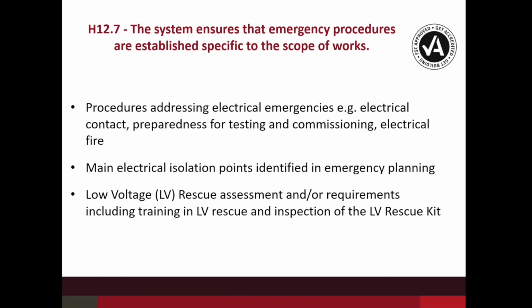So they have a testing frequency. So it's not just a case of, oh, we buy an LV rescue kit and we plonk it in the corner because the guy's working in a switchboard. If that is a potential, it needs to come up, and there's a lot more planning that goes with that, including the training, the re-inspection, certification, confirmation, etc. of the LV rescue kits.